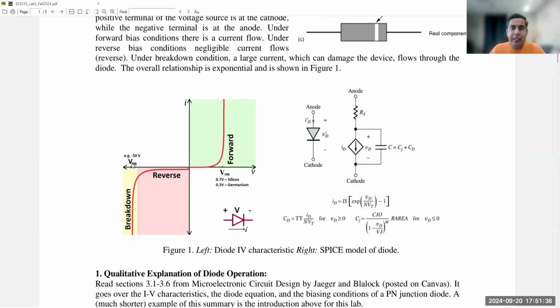And often for a PN junction diode, this is a catastrophic failure. At this point, when we recover, the diode sometimes cannot operate in the same manner as before in the forward bias reaction. Or even if it works, it's not going to follow the same path as before in terms of IV characteristics.